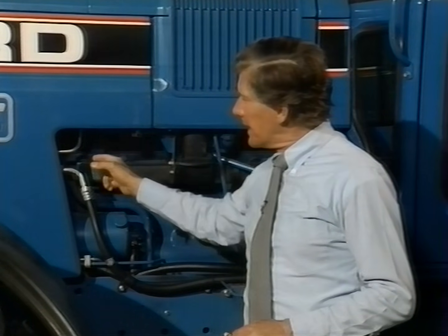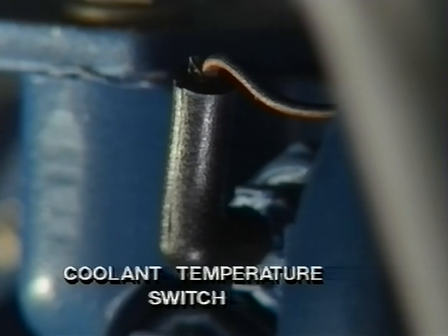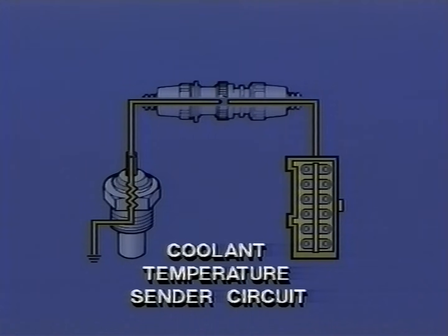The next two input devices we'll look at, the coolant temperature sender and switch, operate in much the same way as the devices used for oil pressure. On TW tractors, these devices are located in the side of the thermostat housing. The engine coolant temperature switch closes when coolant temperature rises above 121 degrees centigrade. The coolant temperature sender varies in resistance with temperature. The changes in resistance are relayed to the EIP, which operates the bar graphs and warning indicators accordingly.